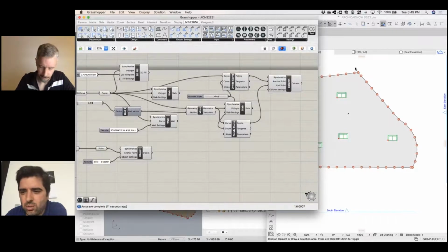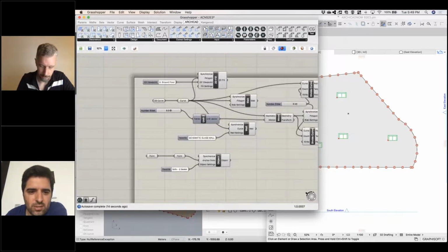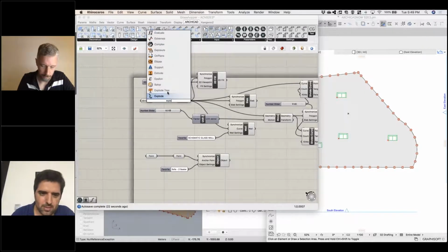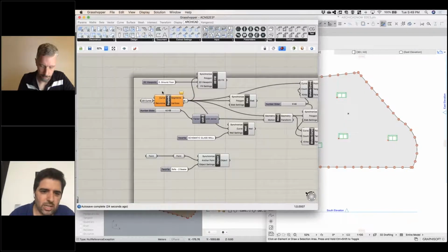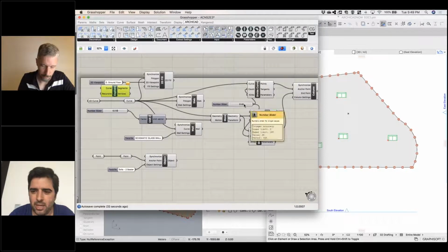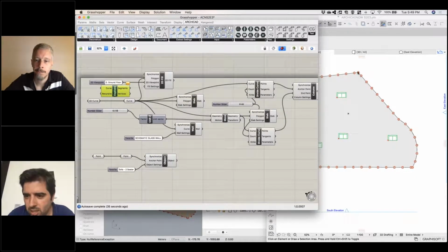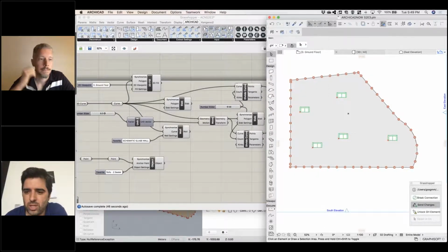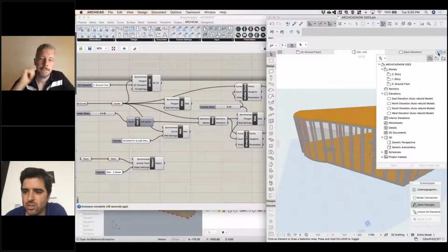If we want to do this, segment by segment, we can do that just by exploding the original curve. We should put here an explode command. And then this would actually divide the curve into segments. And then this splitting that you see happening here would happen in between the segment points. So I won't do that. Otherwise, this will go into very complex. And I think that this is already good enough to showcase the power of this. So just a quick one.